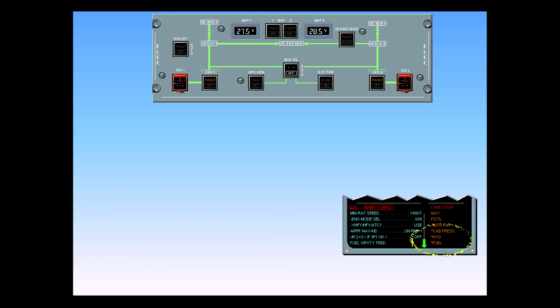Notice also the secondary failures concerning cabin pressure, hydraulic, and fuel systems. There may be other secondary failures that are not yet displayed, since there is an overflow indication, green arrow. We will now jump to the end of the emergency electric procedure to show how the secondary failures can be viewed.